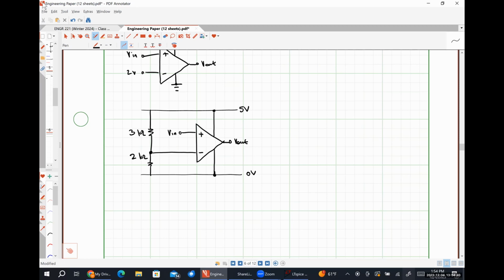So here's our 10. This is terminal X. Here's terminal Z. Here's Y. Here's a 10 over here. So to go from a Y to a delta, because all of the resistors are equal, we'll multiply by 3. So that means we're going to have 30, 30, and a 30. This 30 and this 10 are in parallel, right?